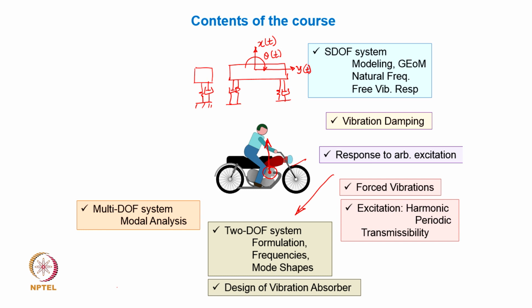So, once we are done with this, we shall move to another topic which is called the transfer matrix method. Of course, this method is a competitor to the finite element method, but computationally this is much simpler and easier to apply. So, we shall have a brief look at the transfer matrix method for solving vibration problems.